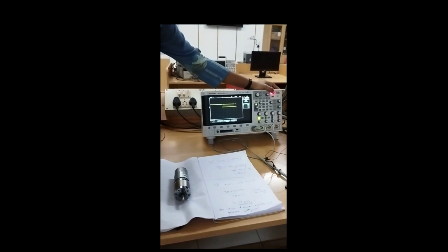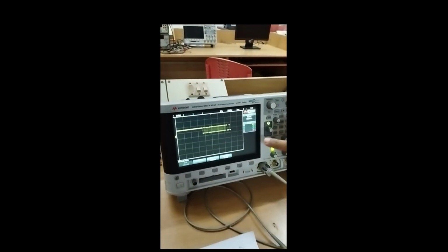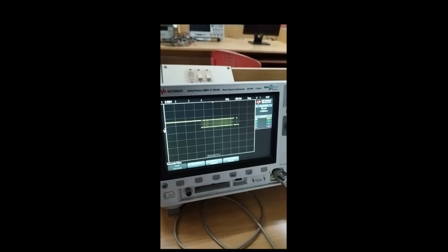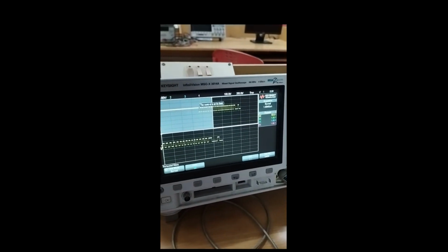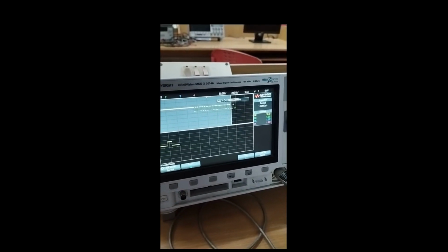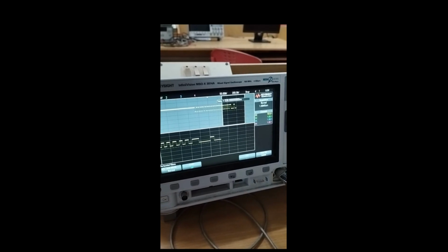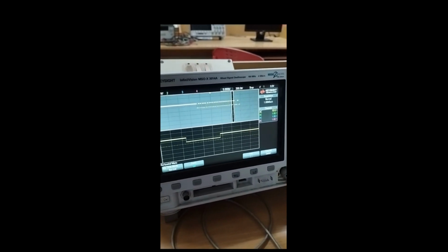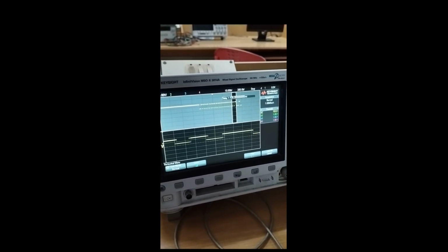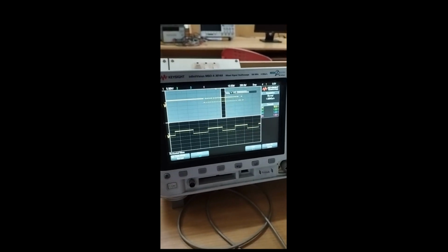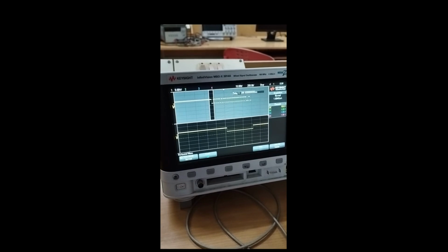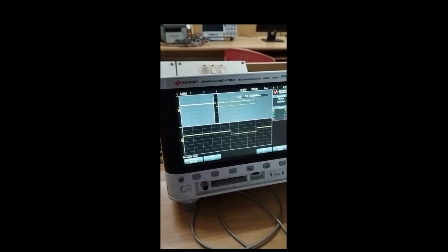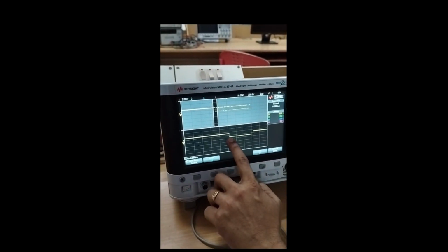For the 90-degree turn, it produces this many pulses as per our discussion. As you see here, these are all the pulses from this waveform. These are all the pulses which were produced by the encoder for the 90-degree turn. We are expecting 30 pulses per 90-degree turn. So let us start counting the pulse falling edges.